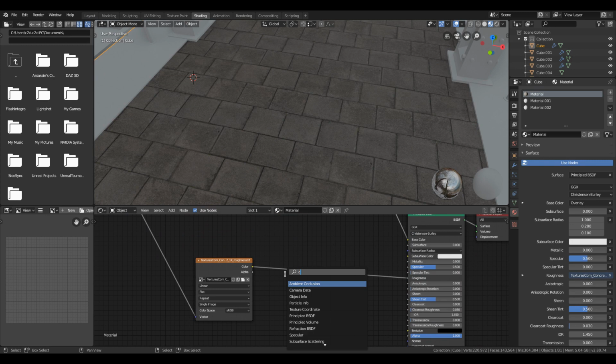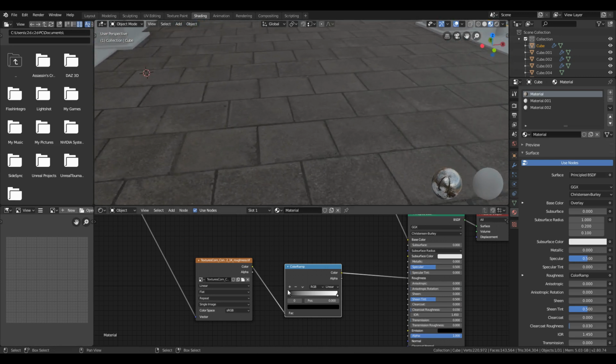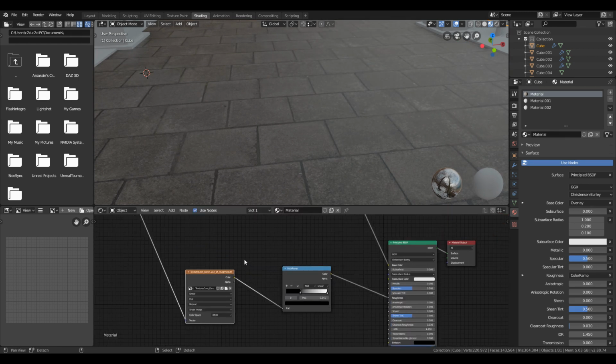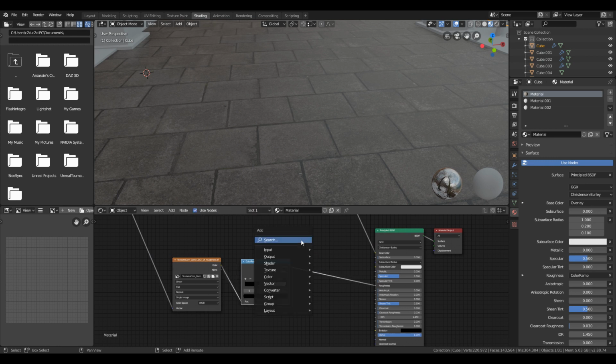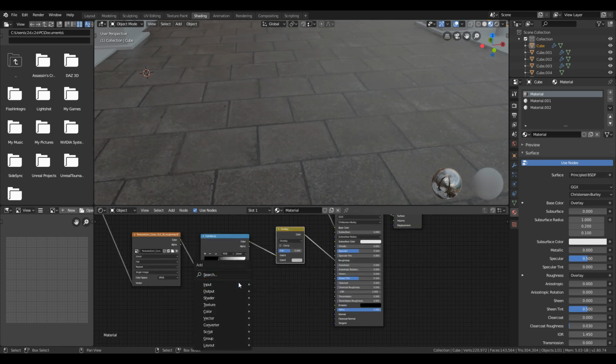You need to repeat the process for each and every texture you want to plug in for the materials. After roughness, add a color ramp to control the roughness based on the grayscale of the texture and play with its pointers to have different roughness values on the floor. Then add Mix RGB after the color ramp and change it to overlay. And then search and put the Musgrave texture and color ramp in the Mix RGB.